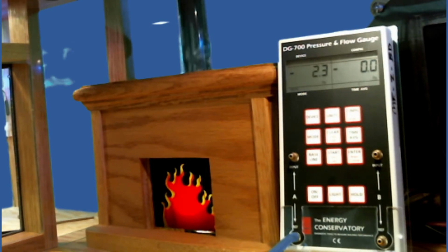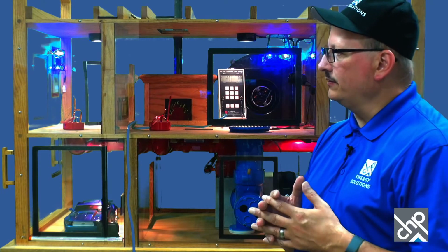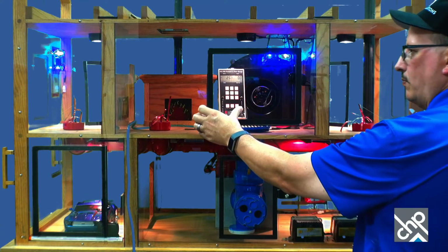And then the smoke goes back out. So, and then I'll close it back. So you can see that pretty good there. So I'm going to turn that off. And now you see how the exhaust fan now, and the manometer, of course you can see the manometer there, we're at minus 2.5.